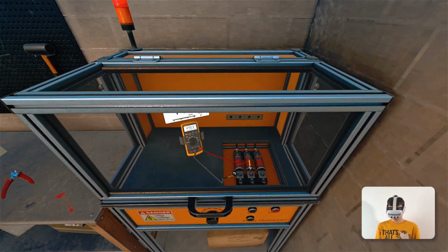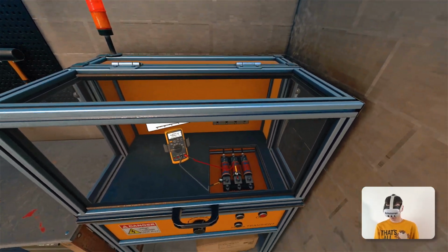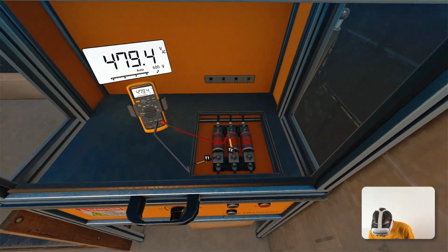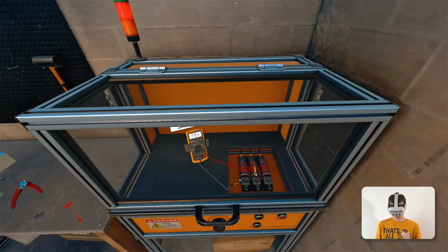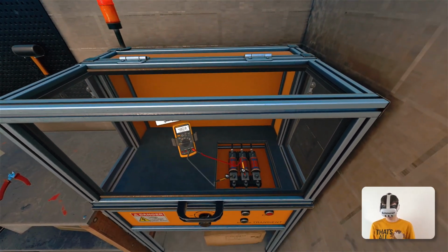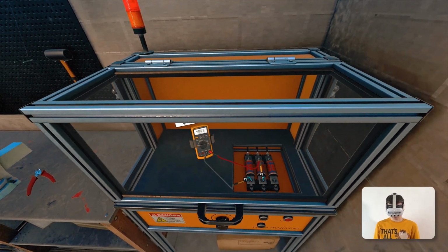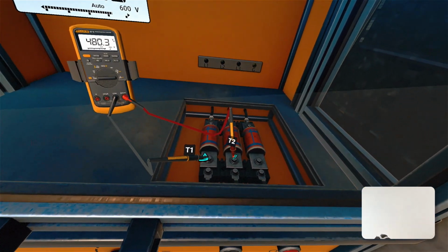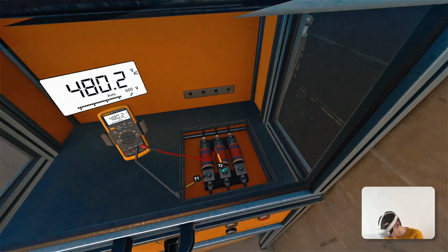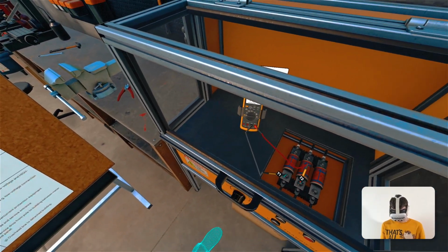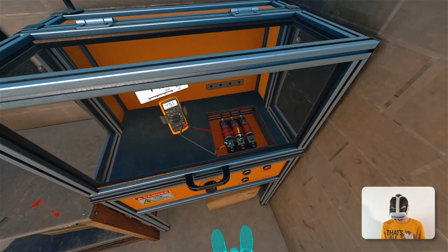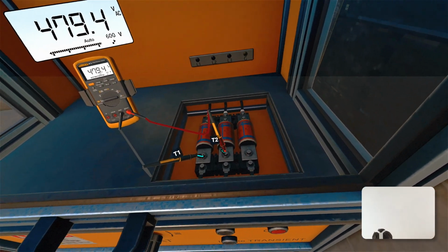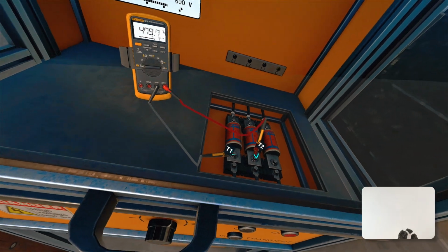Take a step back and observe. The transient will occur shortly. That was fast and intense, but let's take advantage of our virtual environment and replay the incident in slow motion. When the transient occurs, currents as high as thousands of amps can flow for several microseconds. At this current level, the tips of test leads superheat and probe tips start to burn away, drawing an arc from the contact point to the probe tip. The technician sees a bright blue arc flash and at the same time the bang from the arc exploding inside the meter.